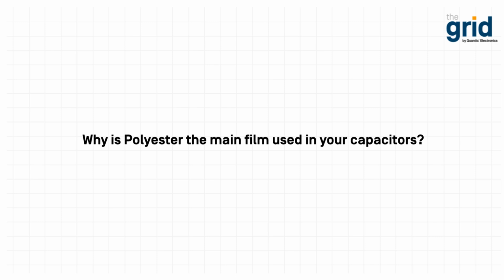So Pactron is fully dedicated to the high reliability power market. Most of our customers do require a minimum of negative 55 to positive 125 degrees C operation. And with our unique construction, we can still use the polyester dielectric for AC applications. So that's the main reason that we use polyester.